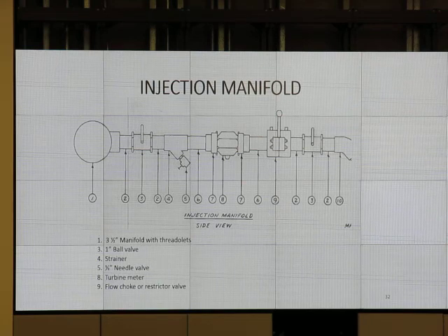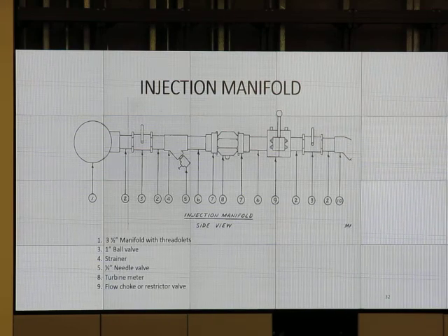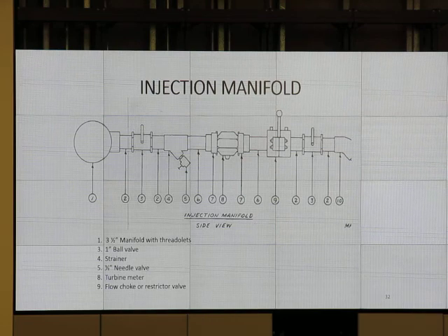So the design I'm talking about says let's place the meters on a header. Back there on our distribution system where we have a header, I've got 10 wells. If I want to adjust the rate on any of them, I go to the header and I can adjust and balance there. If I have my meters out on my well, I can still adjust and balance, but I've got to go to every well and adjust a rate.